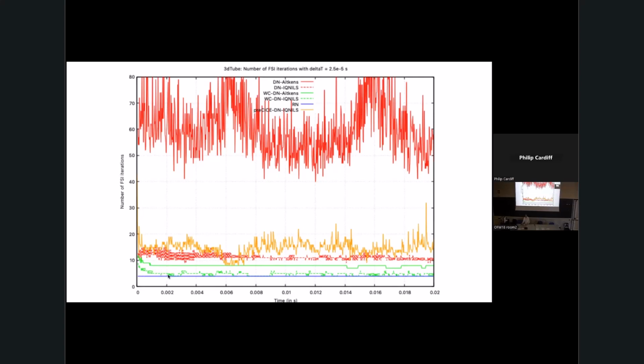And in this case, once the time step's small enough, the Robin approach is really efficient. If you have a very small time step, the Robin approach, in this case, takes exactly 5 iterations for every time step, so it converges really rapidly. The way the Robin approach works, some assumptions it makes only make sense for small time steps. So in this case, this smaller time step ran faster than the larger time step, because the larger time step was taking 50 iterations and this was only taking 5. So a smaller time step can actually make your overall solver faster in FSI.